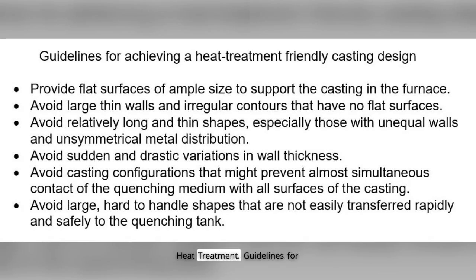Design for heat treatment. Guidelines for achieving a heat treatment-friendly casting design are shown in this figure. When these guidelines cannot be followed, the designer is advised to consider the selection of an alloy that is suitable for lower temperature aging-only heat treatment or an alloy that is self-aging.